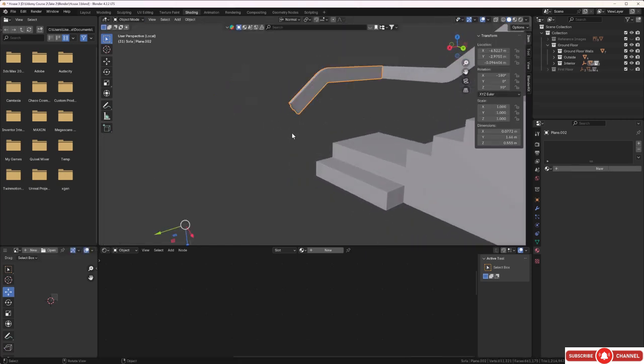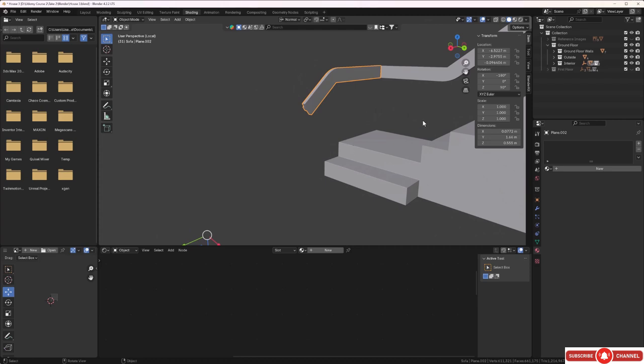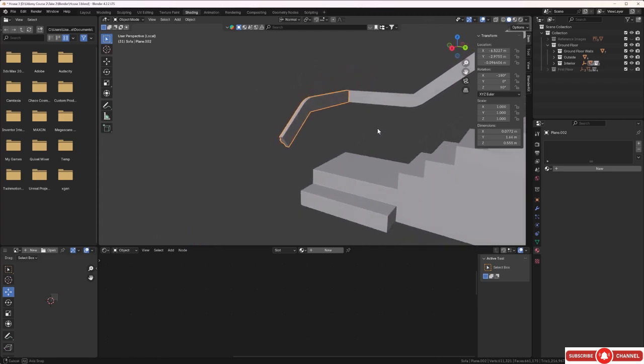Okay, so let's tap out of edit mode with that one, and let's look at the scale on that one. And the scale is a little bit out, so I'll press Ctrl A and apply rotation and scale. Let's just check this one more time, and that one's good. Let's find these items now. And they're here in the ground floor. Let's click on interior, and they're right here.